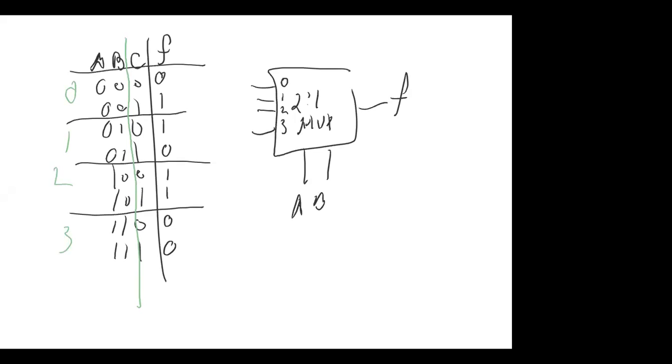Alrighty then. So what shall we write for the inputs now for the multiplexer? So for 0 would be C. Yep, 1 would be C prime. Yep, 2 would just be 1 and 3 would just be 0. Yep. That's it. You did it. That's the whole thing. So that's a 2-to-1 multiplexer implementing a 3-variable truth table.